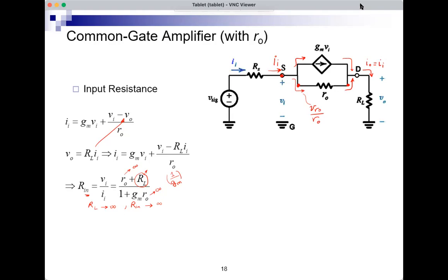So why am I reminding myself of that? Because in the amplifier models, when we try to model an amplifier, and there is a load connected at the output and a source connected at the input, the model for the amplifier assumes that the input resistance inside the amplifier, the output resistance, and the open circuit voltage gain, all of them don't depend on what's connected to the amplifier.